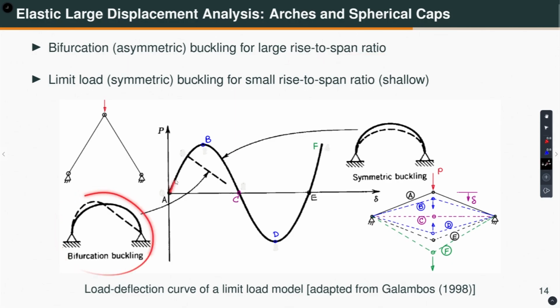So, the force displacement relationship is going to be like this, and then all of a sudden there is a bifurcation of equilibrium, okay. Later on in the course, when we talk about nonlinear static analysis, I will show you that if you do a load control test, then it will go through like this. So, you come to point B, that means you keep on increasing the load, you are not controlling displacement.